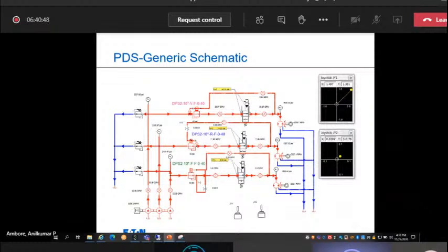By running this simulation, I can understand that the V spool will give me 42 bar pressure with a speed of around 9,000 RPM, whereas R gives me 14 bar delta P with a speed of around 3500 RPM.